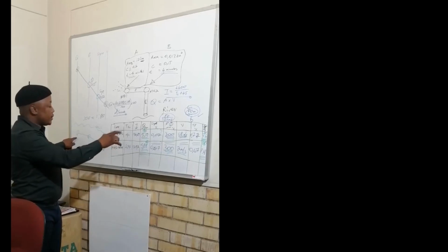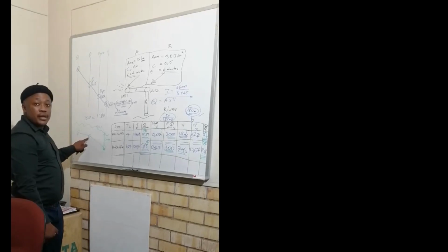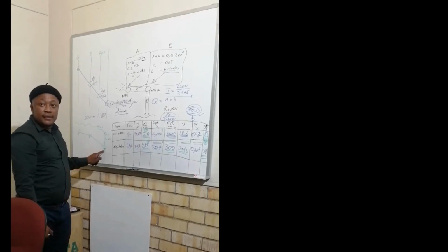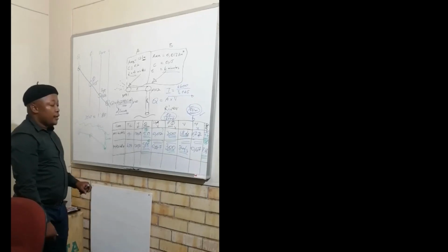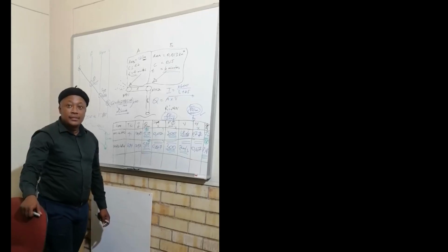And understanding that you've already calculated the slope of the pipe and you know the distance of the pipe, you simply subtract, when you go down, the slope multiplied by the distance, and then you get the invert level there, and then you do the same and get the invert level there. Then you'll be able to understand the long section, how it is shaping up for the same pipeline that is in plan for you in that context.